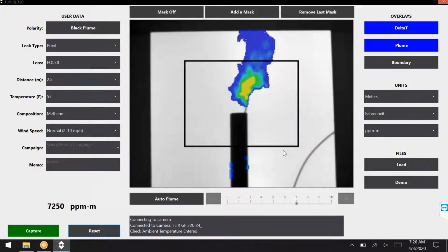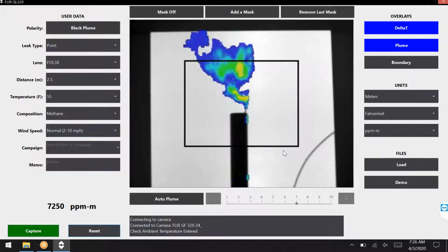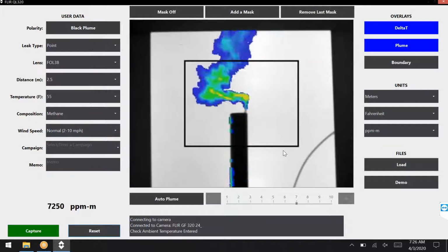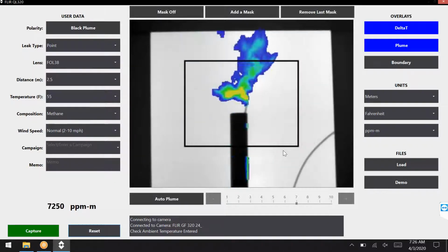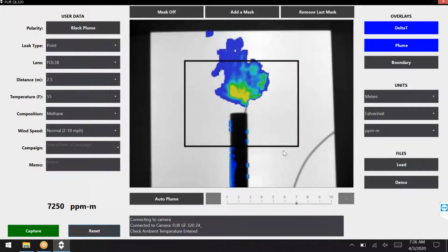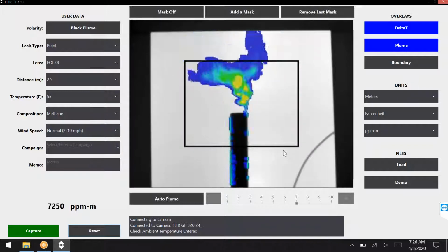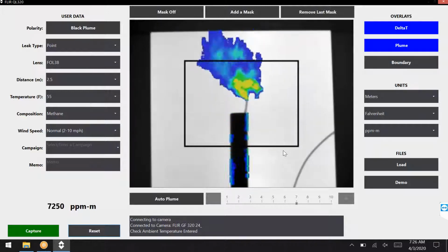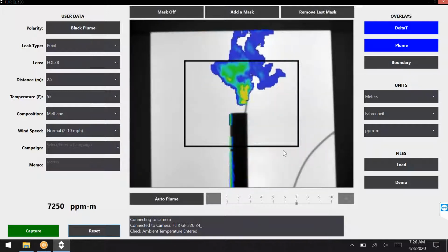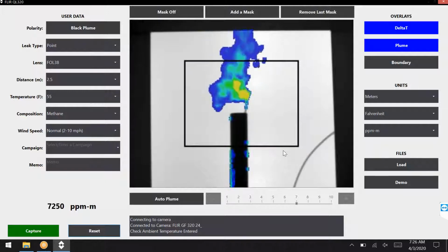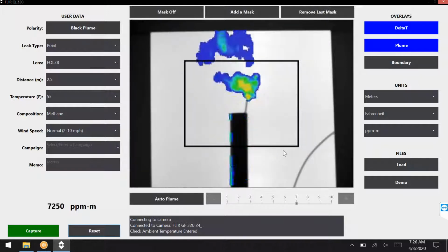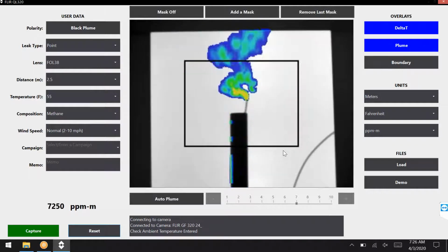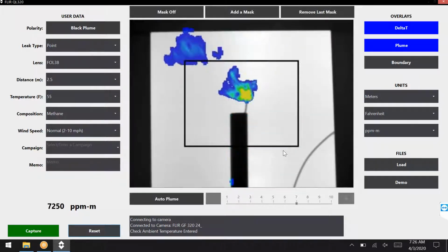What is the average accuracy level of the ppm measurement? I think that's a tricky answer to get into when you talk about average accuracy. Because this is new, we have not been able to do field studies with third parties like Concawe yet. I would point it two ways. One, I would still point to the old Concawe and state that our solution was a plus or minus of 6% standard deviation, where theirs was over 30, and theirs was over 30 while being directed to the leak. Let's keep that in mind.